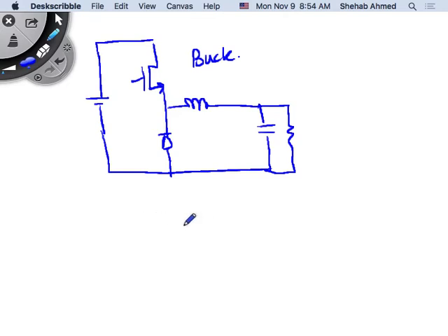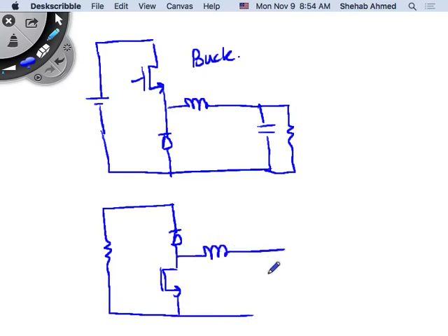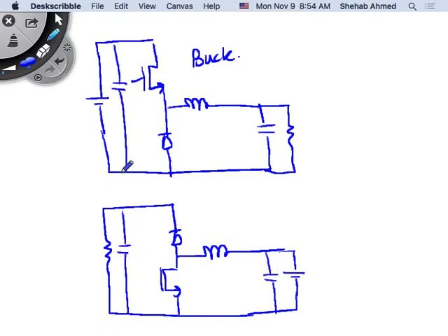For my boost converter, I said I have to switch the MOSFET and diode, but here I will add my load, here my inductor, my input source. It does not matter if I put the capacitor here or not. I will justify that sometimes we need it. We can add a capacitor here and here. We can size it. If there's ripple current or ripple voltage, then there's a need to put a capacitor. I'll prove to you that there's always ripple voltage in this case. But regardless, now let's see what's happening. I want to draw this waveform. VP1.